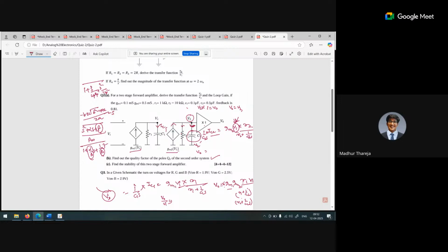Sir, since the equation is already positive, the quadratic equation that is formed would also be positive. Having a quadratic equation with all plus signs automatically means the poles would be on the left half of the plane. So do we need to calculate the exact values, or is that explanation fine? No, you have to find the stability of the two poles. You have to identify only the stability. If you are sure that your poles lie in the left half only, you can directly mention that if the poles lie in the left side of the S plane, we can say the system is stable.